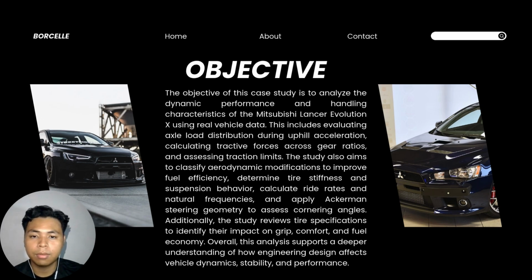Alright, the objective of this case study is to analyze the dynamic performance and handling characteristics of the Mitsubishi Lancer Evolution 10 using real vehicle data. So this includes evaluating axle load distribution during uphill acceleration, calculating tractive force across gear ratios, and assessing the traction limit.